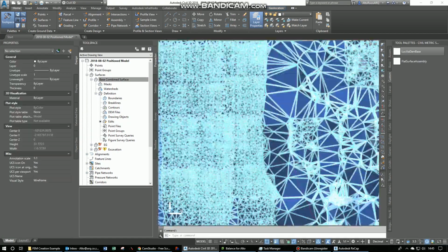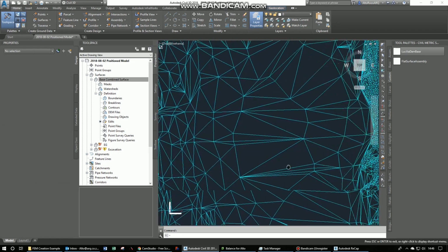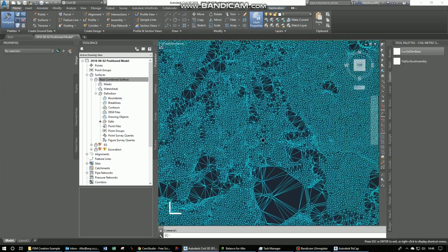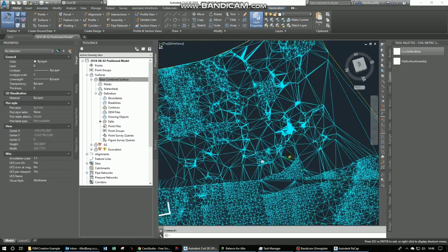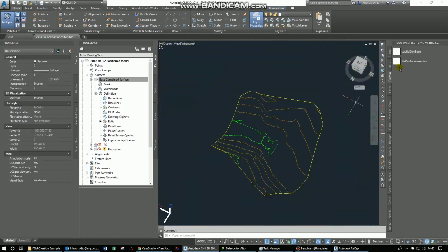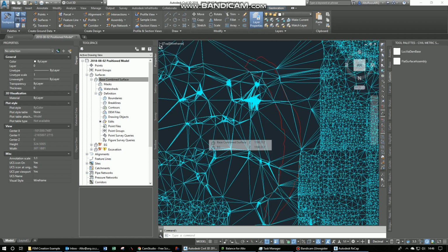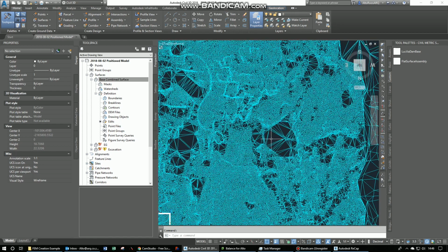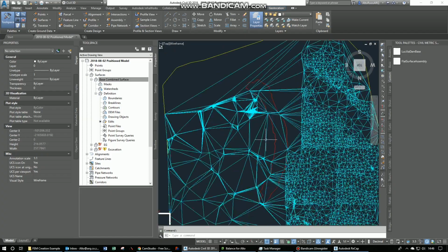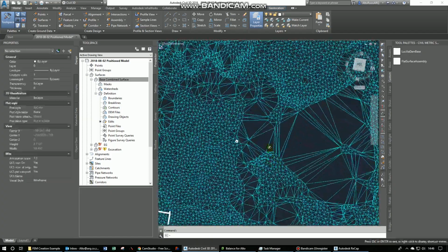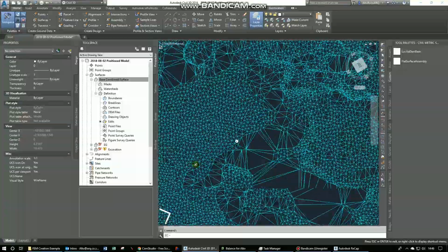As you can see here, the mesh we've got is extremely fine, and then less defined in the excavation plan, and then again very, very fine on the downstream side of that dam. I've got the zoom, or the detail distance thing, set on in Civil3D, so as I zoom out the detail becomes less, just to keep my PC running relatively okay. But yes, there you can see it, very well defined. But let's refine the surface for now.